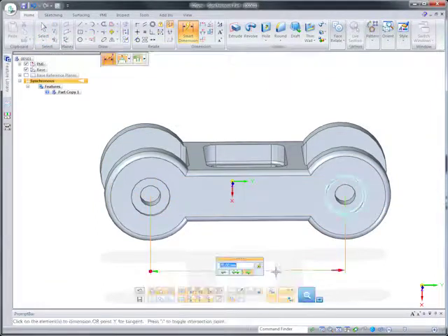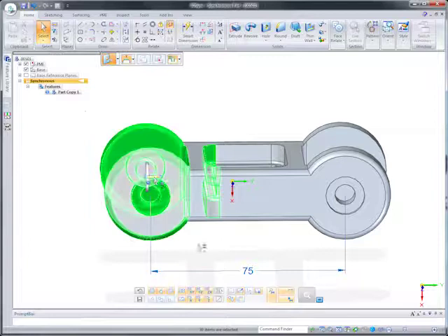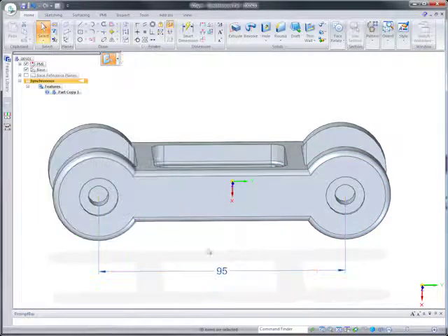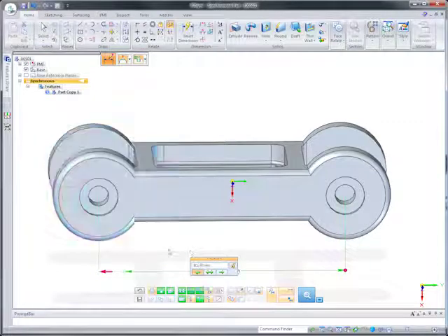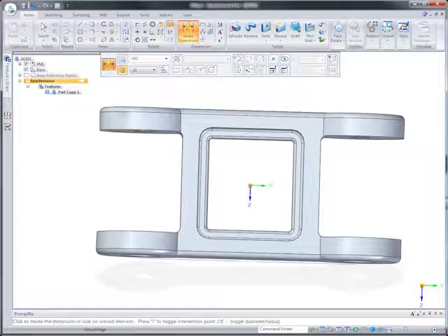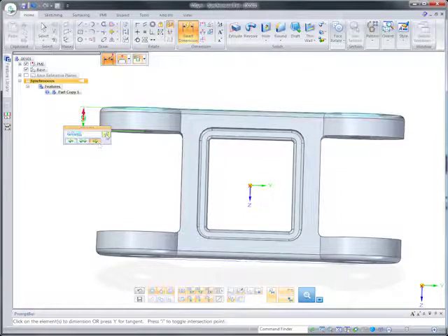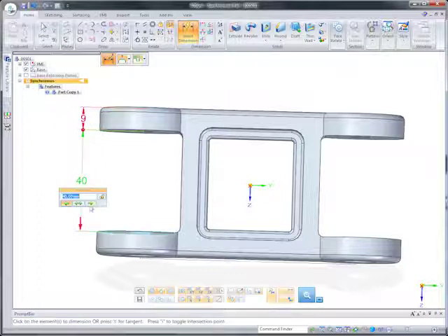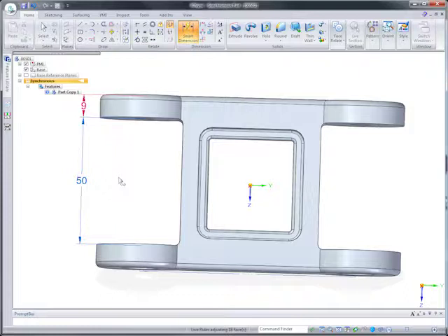Let's make some dimensional edits to this SolidWorks part. Unique to 3DSync are 3D driving dimensions, which can be applied between key geometric features. When added between the alignment holes, we can edit the spacing directly. 3D driving dimensions can be placed in a stacked configuration and locked to preserve distances. As the interior clearance is modified, notice how the linkage thickness remains.